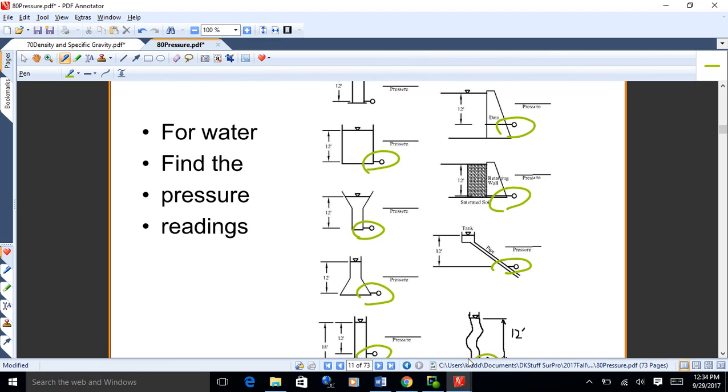The one thing I've noticed here is on retaining walls. They have to be a little careful, because you get all this pressure building up behind a retaining wall. It can just push the wall over sometimes. If you look close at the bottom, they'll put in little PVC tubes, about 4-inch, maybe less, that run through the retaining wall. They put some filter fabric on the dirt side to keep the soil from washing through, and they just let that water seep out from behind the wall because they don't want the water building up. It builds pressure, and that can end up really pushing hard on the wall. They can handle the dirt stacked up behind it, but the water can really add a lot of pressure.